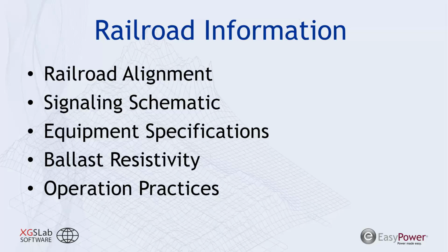For example, they may have the ability to operate with an insulated joint that is defective or in need of repair. That creates significant imbalance in the rail-to-rail voltage and can dramatically affect the downstream signaling when you incorporate AC interference into that. Or you could have train operators that will occasionally stop the train at different junctions, crossing over those insulated joints, potentially elongating the exposure length of that railroad to the transmission line.